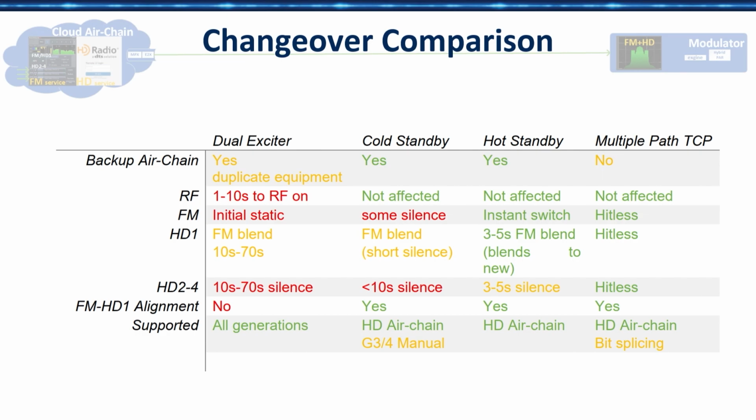But the HD is not perfectly aligned, and some receivers will still hunt for the original HD stream for about 10 to 70 seconds. If you were to tune them off frequency back on, they'll be right back on, but they're hanging on to the last one. So it can actually take a while before your HD service is back on. So with our standby mechanisms, that becomes much better.